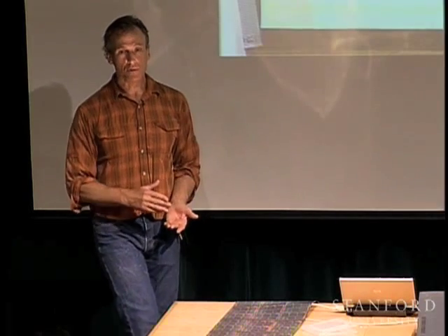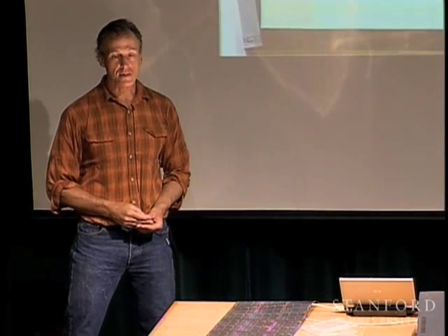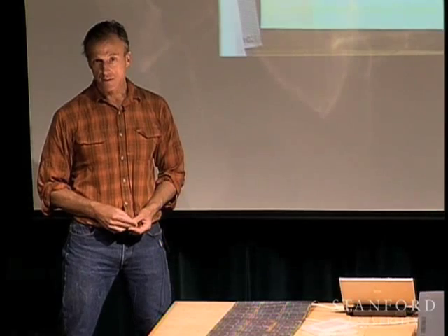Four different tools. Because some tools are faster, like the imprint tool is very fast, you only need 1 of those. You need 4 vacuum deposit or etch tools to service that one. But you only need one of each for the pilot. Well, for pilot, actually, you still have the same problem. Let's say that the imprint tool runs 4 times as fast as a reactive ion etch tool. Typically, plasma tools are the slowest, the wet tools are in between, and the imprint tool screams. It's very fast.